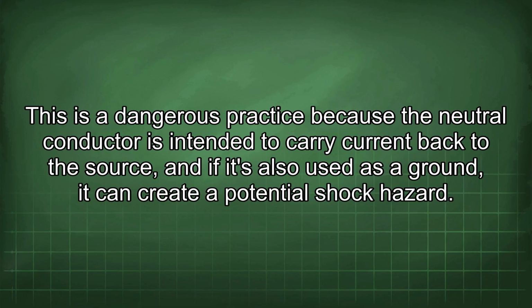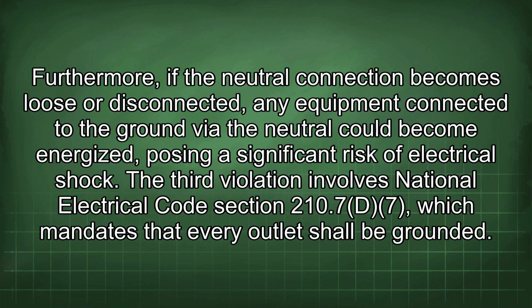This is a dangerous practice because the neutral conductor is intended to carry current back to the source, and if it's also used as a ground, it can create a potential shock hazard. Furthermore, if the neutral connection becomes loose or disconnected, any equipment connected to the ground via the neutral could become energized, posing a significant risk of electrical shock.